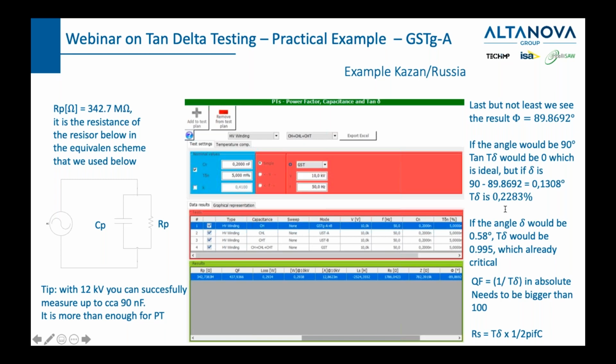One important thing I wanted also to tell you when doing this test, especially when you're generating high voltage on any of the sides: the cable which brings high voltage shouldn't be touching anything, because in that case, sometimes, due to the stray capacitance, you might have some issues with generation. So the cable which brings the high voltage to the testing point should not be touching anything.